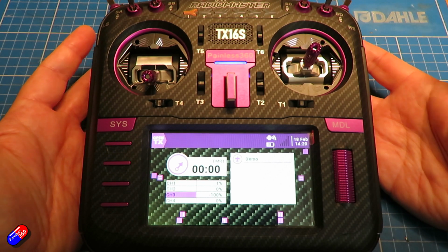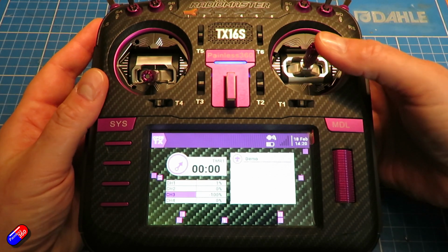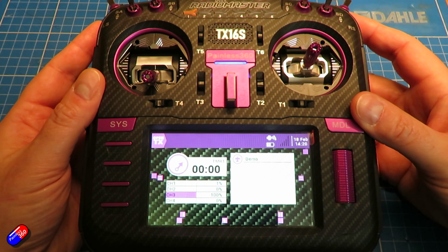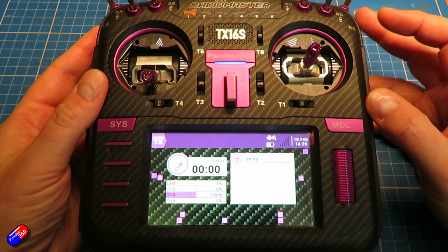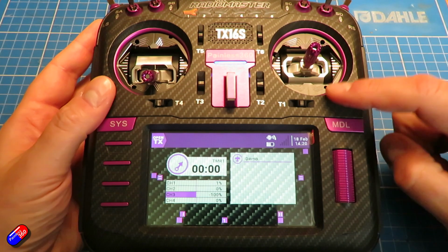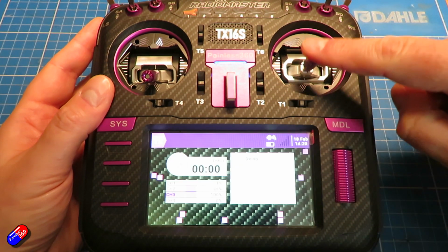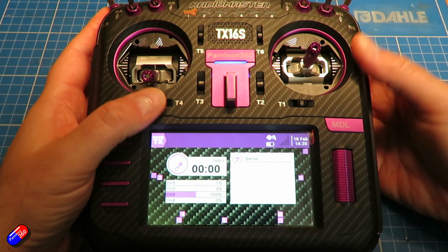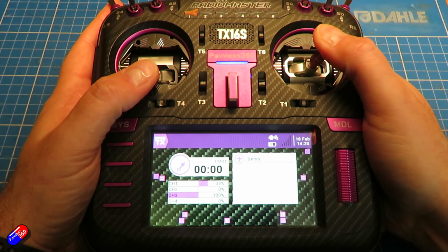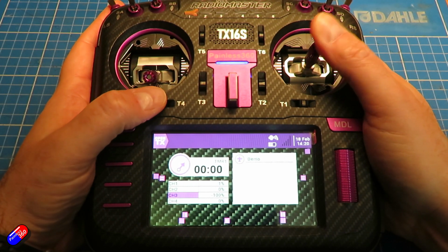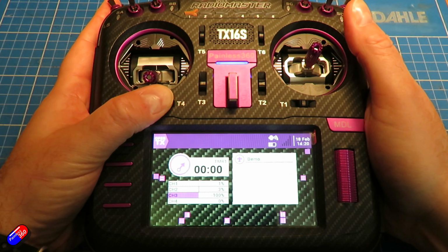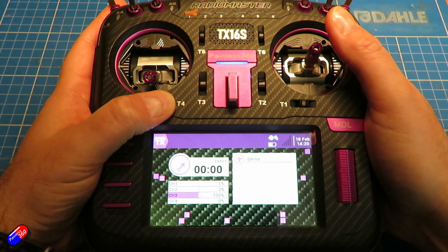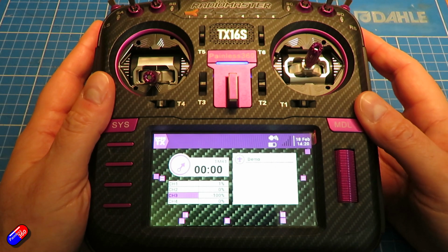And if it's only a slight bias towards one side or the other, if you've got enough height, then you've got time to kind of jump on if you're not using something like the instant trim feature that I've just shown. However, a much more sensible way to do it is to use something called cross trim. So rather than have the trims by the control they're interested in, have it on the other side. So for example, have the aileron trim over here. So say for example, you're flying and you need that little right hand pressure, you can then add that using the trim over here rather than over here. And that way you don't have to take your finger off the sticks. And that can be a much, much safer way to do it.